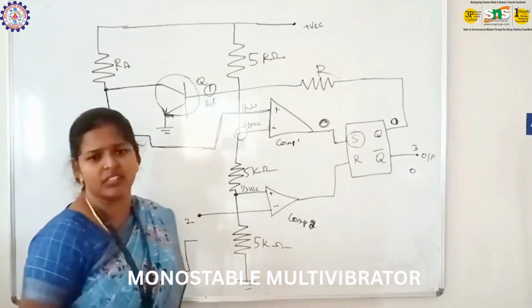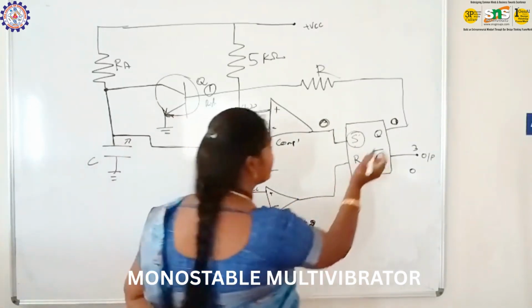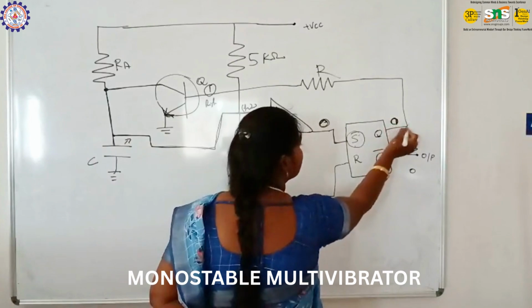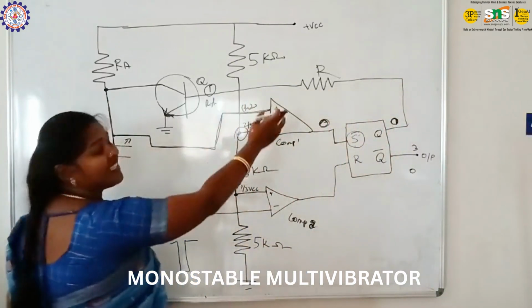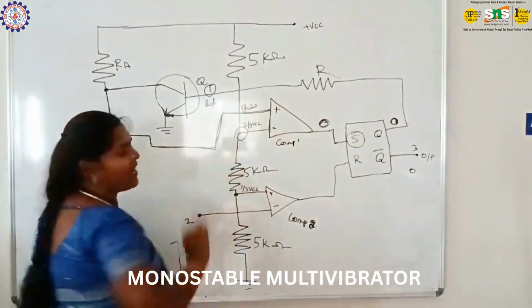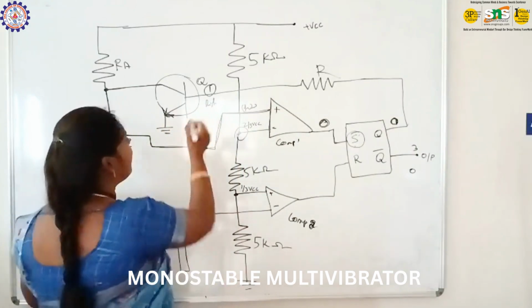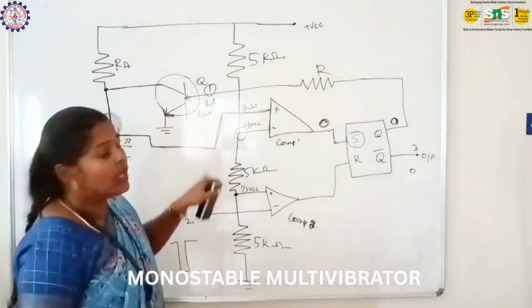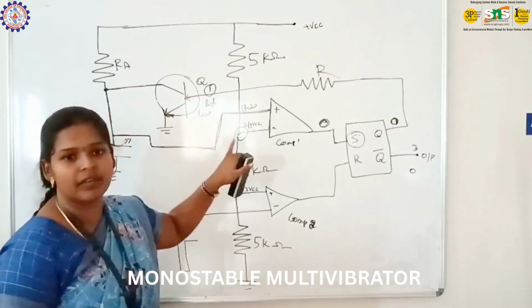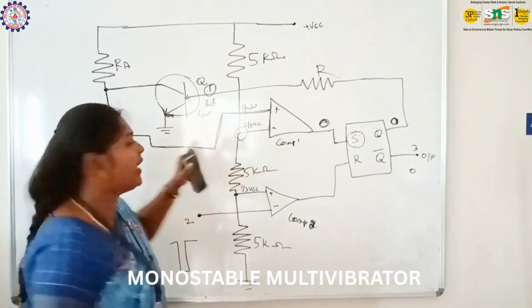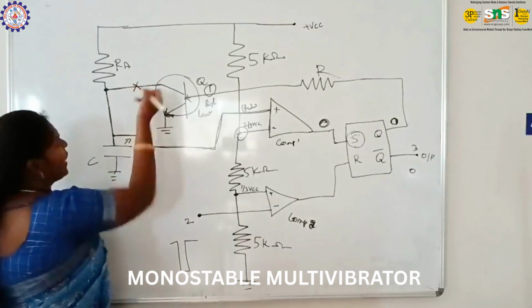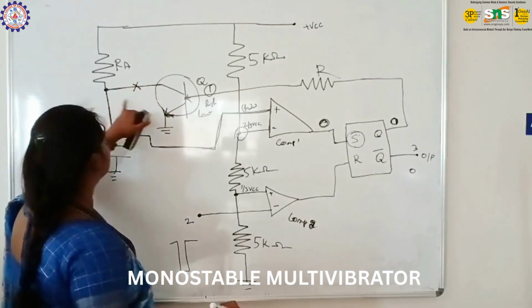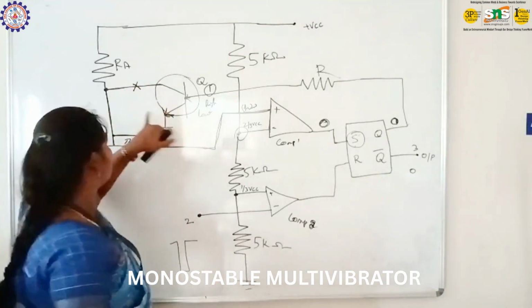This is the common function. When it is 0, this 0 again flows through the resistor and is given to the transistor. Now the low signal is given to this terminal, so the transistor will be disabled. Now there is no connectivity between this pin and the transistor.